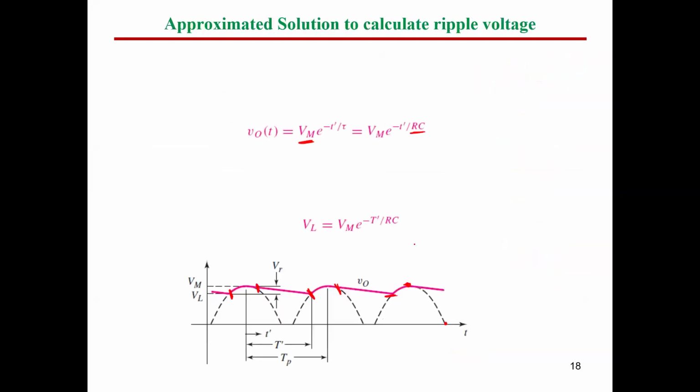After the transient part, you have the steady state part, where this part represents the capacitor voltage while discharging. At this point, referred to here as VL, the capacitor voltage becomes equal to the supply voltage. So the supply voltage is going to be higher than the capacitor by the turn-on amount, and this turns the diode on again.